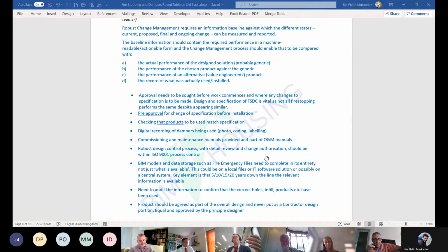And the other thing I think as well to bear in mind is that we have PT slabs now. Compartments on horizontal have been pushed down to the hilt, especially on resi. These details need space. PT shrinks more, moves more.